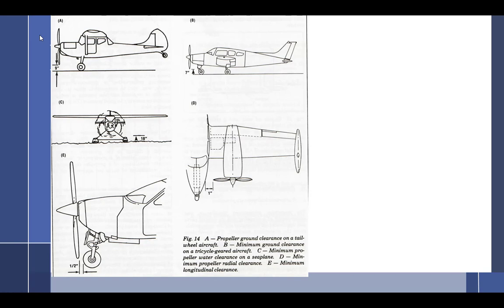Oh, speaking of, I'll make a step back here. I did mention yesterday where we got all of these dimensions was from FAR Part 23. But here's the problem with FAR Part 23, which is Certification Standards Normal Utility and Aerobatic Category Aircraft, is that the FAA has recently made a major change to Part 23. So for a very long time, the FAA would say, this is exactly how you have to build an airplane. And then they went away about 2 years ago, and they call it performance standards.